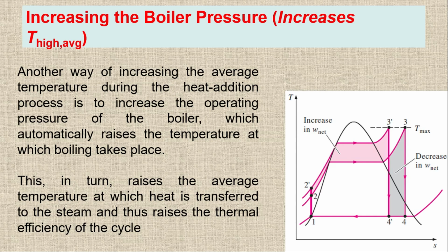These are the turbines or Rankine cycles that are operating above the critical pressure, and they have thermal efficiencies of around 40% for fossil fuels and around 34-35% for nuclear plants. Normally we are using plants where the pressure is below the supercritical one.